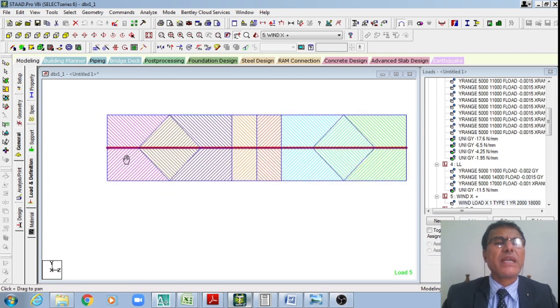Therefore this beam is getting a load from this piece and this piece, right? Whereas this beam is getting a load from this triangular area of this exposed area, right? And this beam is getting it from this trapezoidal loading, right? That is how these beams are getting it from this rectangular loading, so on and so forth, right? It is so easy for understanding actually, right?